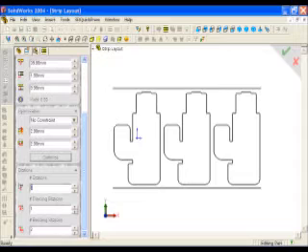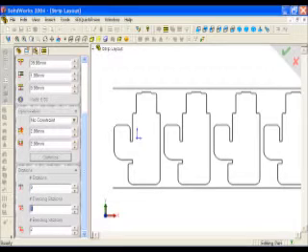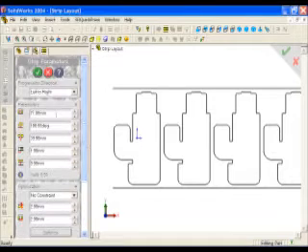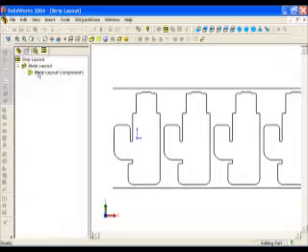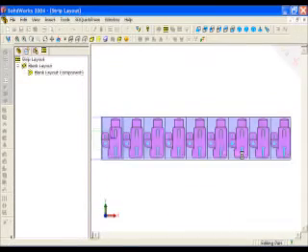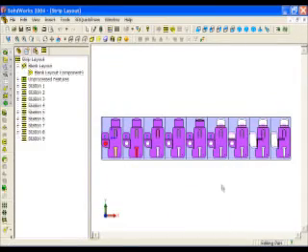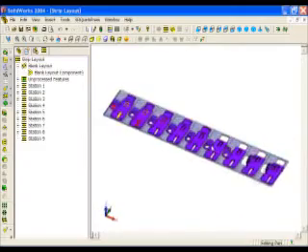We may want to tell it that we need approximately 9 stations, and 4 will be piercing and 4 will be bending. These are just jump starts, they're not required. This puts into play what features already exist in it, and then we can adjust it as we go. With that completed, we have our strip laid out.